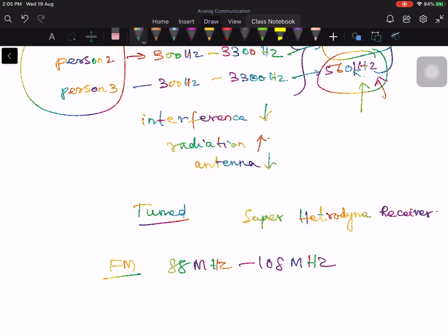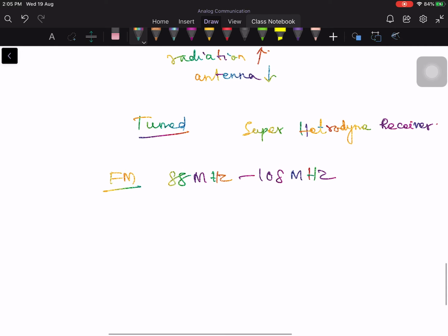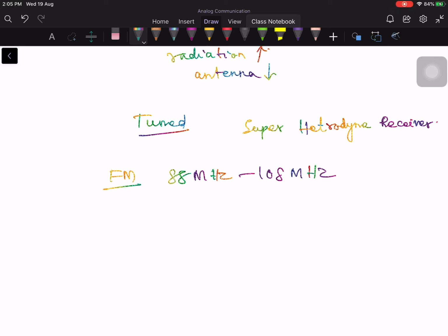So the use of the modulation process helps in shifting the given message signal frequencies to a very high frequency range. See here, very high frequency range in the sense that it can occupy only a negligible percentage of the spectrum. For instance, at 100 or let's say 1000 kilohertz, a 10 kilohertz wide message signal represents 1% of the spectrum.